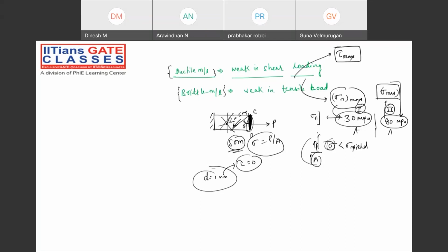So in the actual condition, when the load has been applied on that particular plane, suppose tau is there, that 1 mm diameter will not be sufficient to survive that particular stress value. But suppose you have designed for this 5 megapascal and you give the diameter as 10 mm. Whatever the loading condition the customer applies, your material will never fail just because of the maximum stress value conditions. In shearing, it will never fail. Understanding?